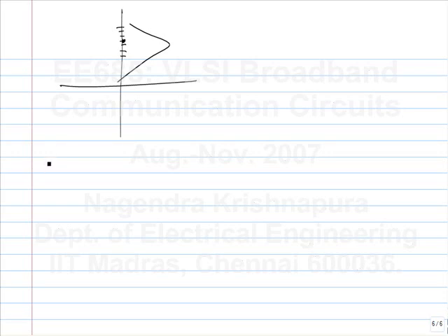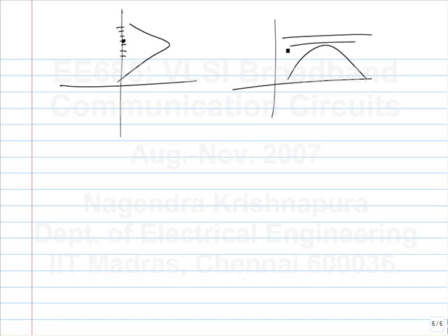In reality you get a continuous time waveform and the eye diagram looks something like this. It can have many possible transitions, 0 to 1 and 1 to 0 and so on. If this is the sampling instant, you get a bunch of values. Now you are considering what you are going to do to these values, whether you will minimize the mean square value of that or whether you will make that equal to 1.